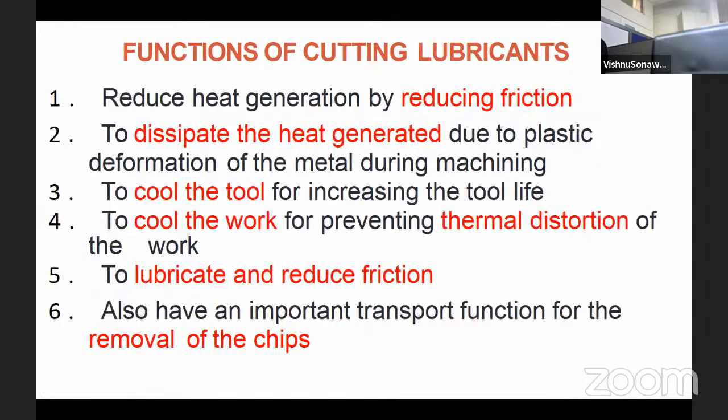Now the function of the cutting fluids for high-speed machining. When we use the proper type and proper amount of cutting fluid, the friction will be reduced, the heat generation will be reduced, and the heat generated will be dissipated due to the plastic deformation of the metal during the machining operation.